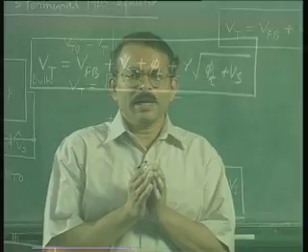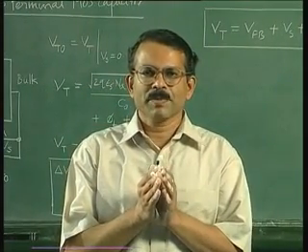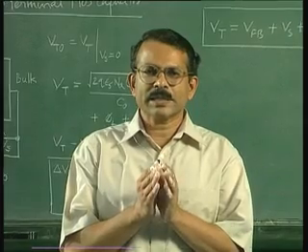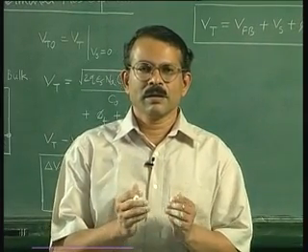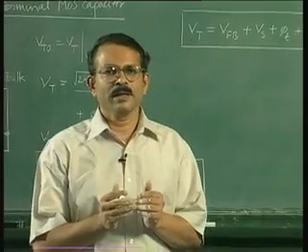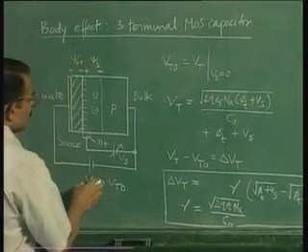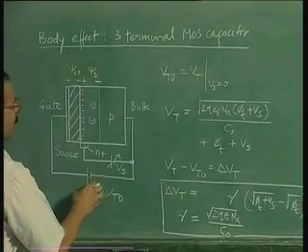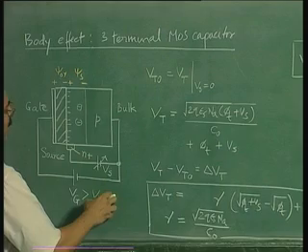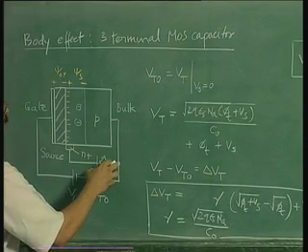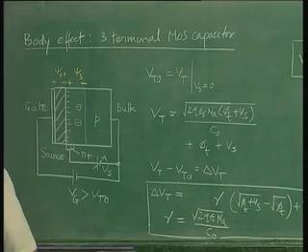In order that we understand the body effect very clearly, we can discuss the same thing that we were elaborating upon so far in a slightly different way. So far we assumed Vg to be constant at a value greater than threshold voltage for Vs equal to 0, and then we increase Vs to see what is happening, and we explained that the inversion charge is going to reduce.